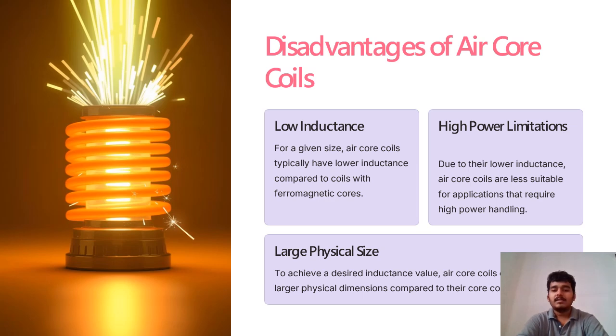Yes, these air core coils have low inductance because there is no iron material, which is a low reluctance material, present at the middle of the coil, so automatically it has low inductance. For a given size, air core coils typically have lower inductance compared to coils with ferromagnetic cores. We can clearly see that the ferromagnetic core is not present in the air core coil, so it has lower inductance.